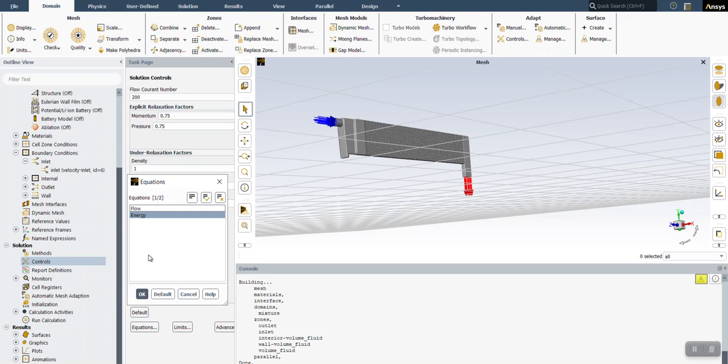So it's going to solve the energy equation for both flow and solid, if you have solid. And it's a valid assumption, especially if you don't have a big gradient in temperature, or the temperature doesn't affect the fluid flow. So with this, it doesn't solve the fluid equation, and it's going to save a great deal, and your simulation is going to run faster.